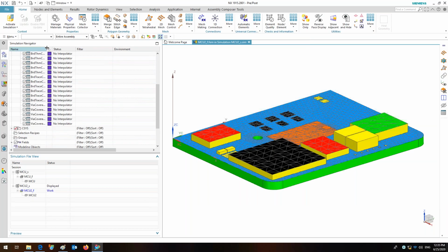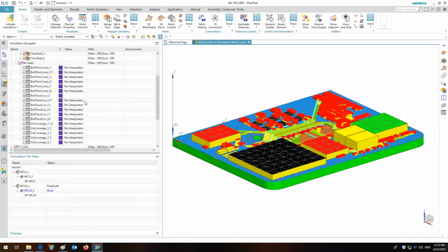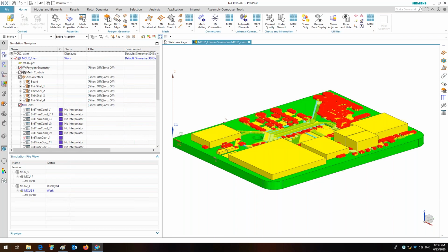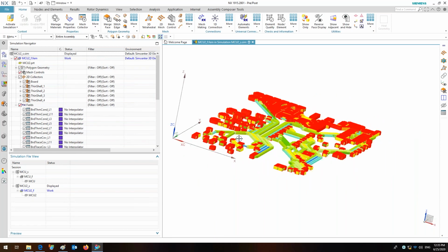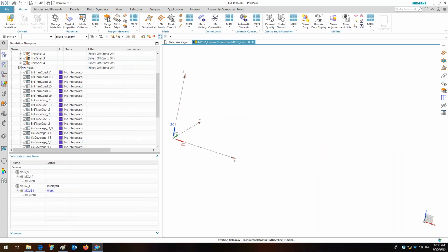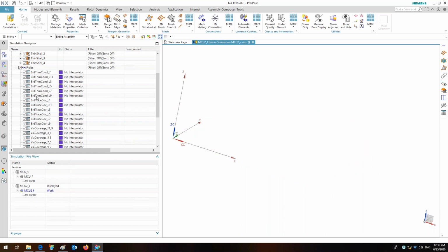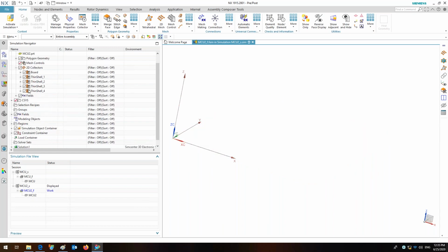And as we saw in the last webinar, we can actually preview these fields graphically in the UI directly. So for layer 1, let me hide the geometry, we can see that the copper content looks something like this, similar to the image we saw earlier. For layer 3, which is a ground plane, it is mostly copper, so entirely filled in. So that is for how the board is modeled.